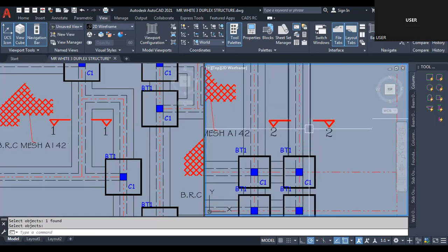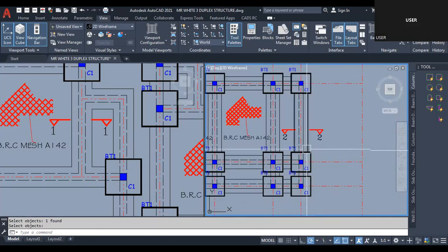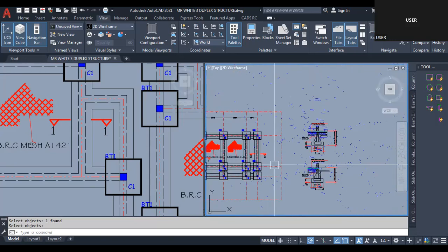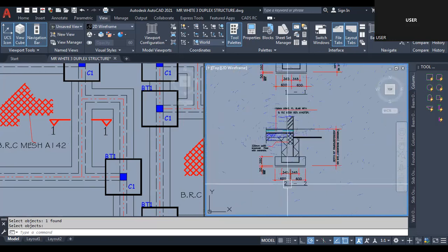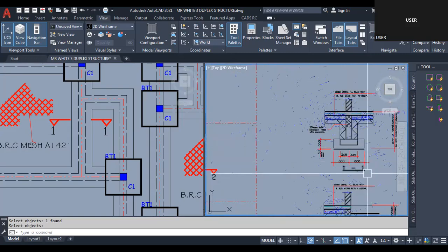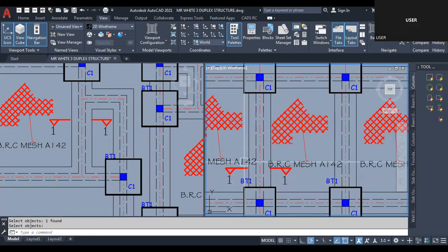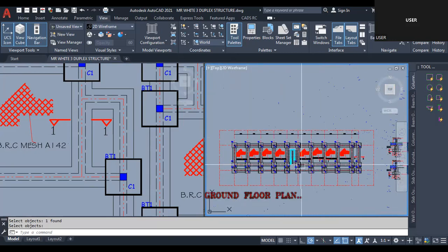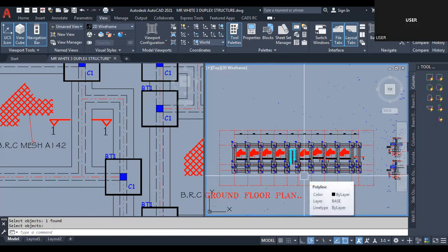So cross section is another challenge most people have. You must understand cross sectioning while you were doing probably technical drawing and the likes. You must have done a whole lot of cross sectioning then. So when you cut that, this is what you see. So this is cross section 2-2, an L shape, and cross section 1-1 in form of a T shape. So this is how your foundation layout is going to look for this particular design, assuming we are using AutoCAD to do our detailing manually.